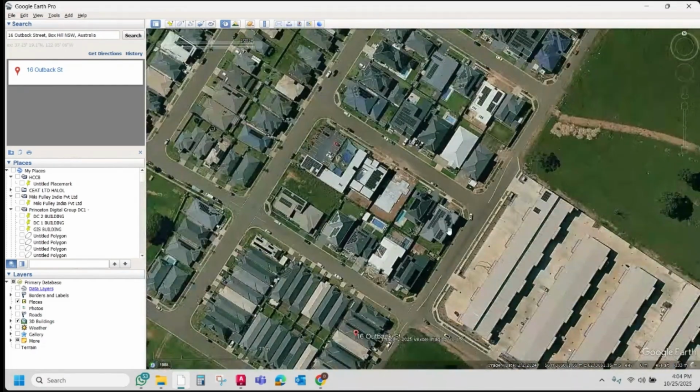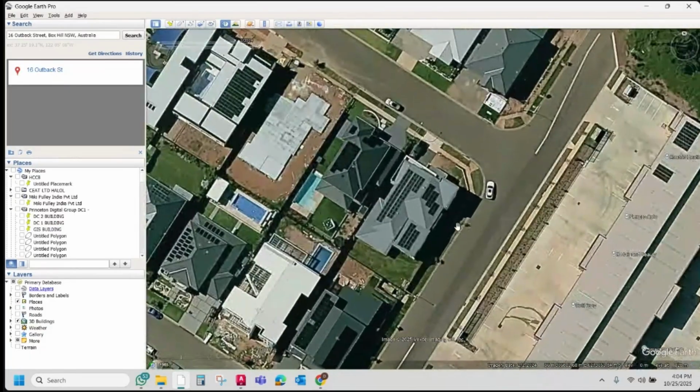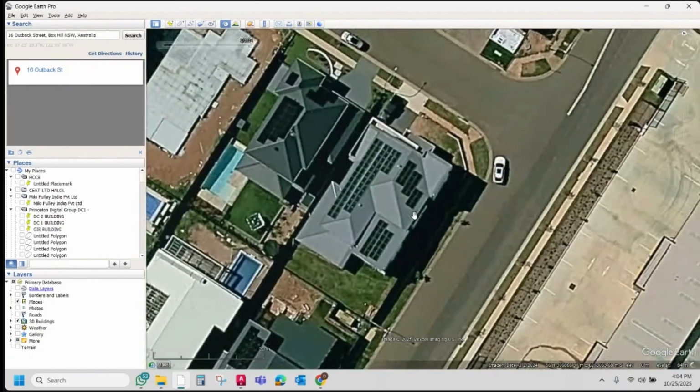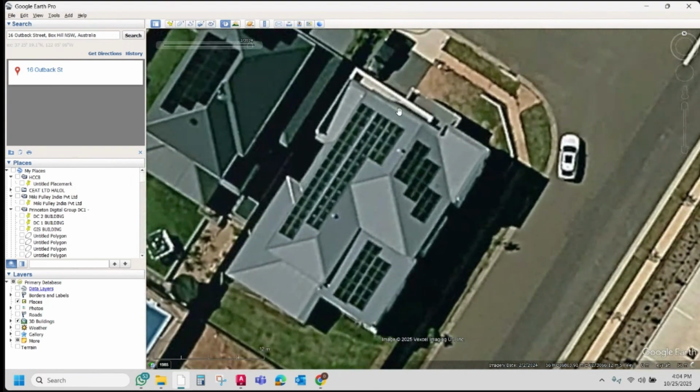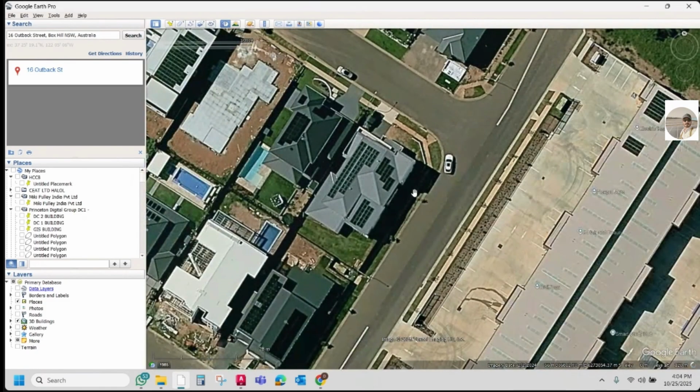So after that site visit, what do you do? When you are doing the site visit, you need to collect the slope, how much slope is there, first, then how much distance is there between two parapet walls or parapet lines, then the total length and width which are required to draw the proper roof. After getting those dimensions we can draw an actual roof, that precise we need to be.